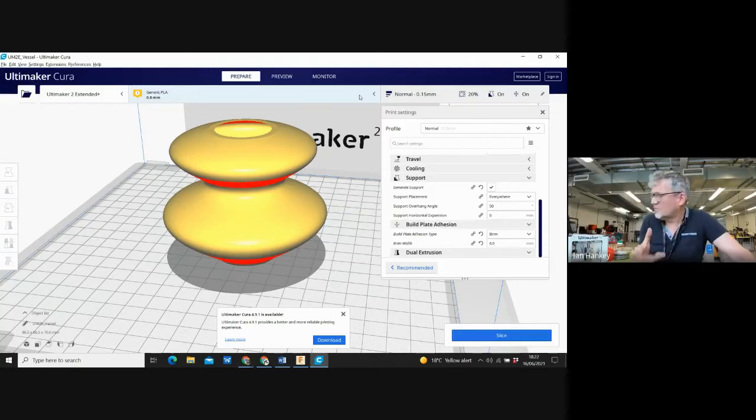The small one, the Ultimaker 2 Go, is only 0.4. And also, I think on the S3 and S4, we probably have to choose the nozzles on the left-hand drop-down menu or the right-hand drop-down menu, because there's 2 of them. So that's true. Each machine will probably have a slightly different selection of nozzle sizes.